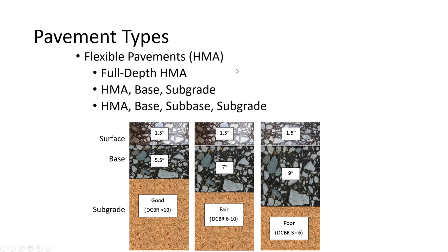And there's really, I mean, people often try other stuff, but nothing's really stuck, so to speak. This is what our pavement sections will look like. We've got a surface mix, which is usually a tighter, smaller aggregate mix. And then we've got intermediate or base, and then we're finally down on the subgrade, right?